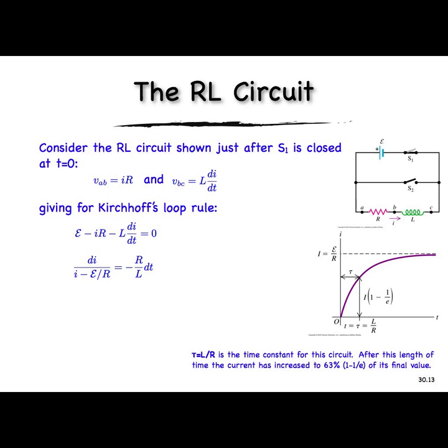And then if we close this switch, the current can now flow around this loop. No longer powered by the battery, but now powered by the inductor, and the energy stored in the magnetic field produced by the inductor, trying to keep the current flowing because of Faraday's law.